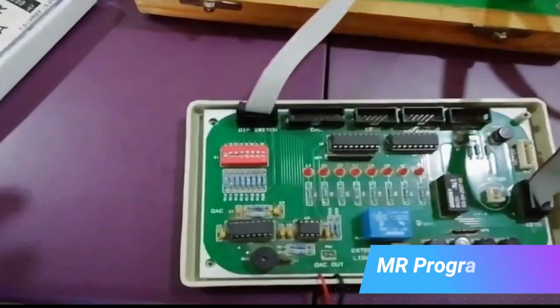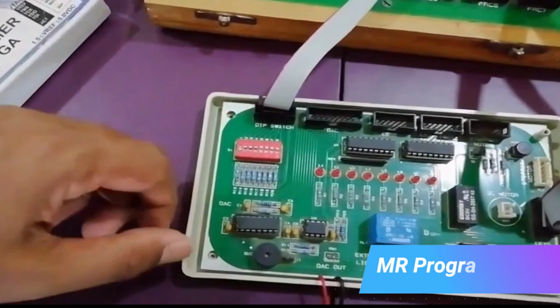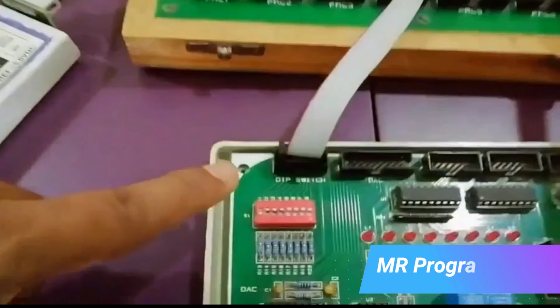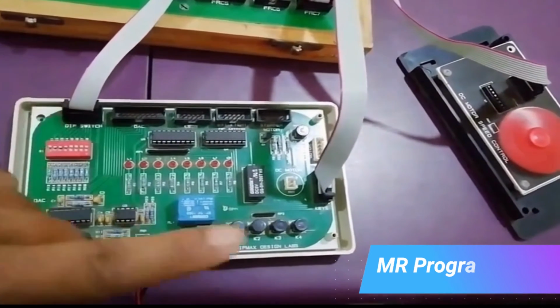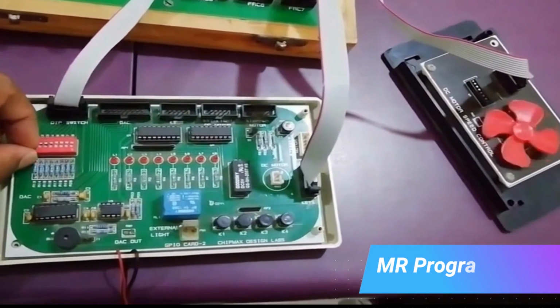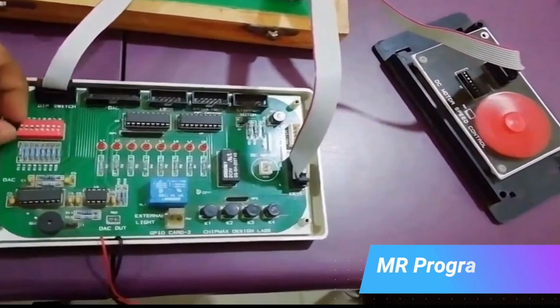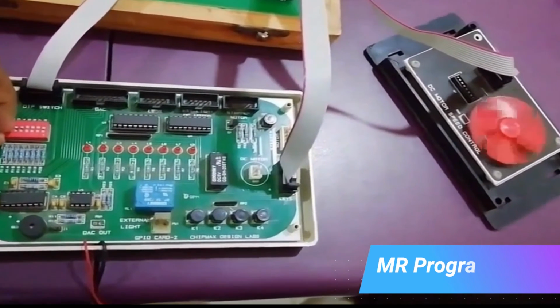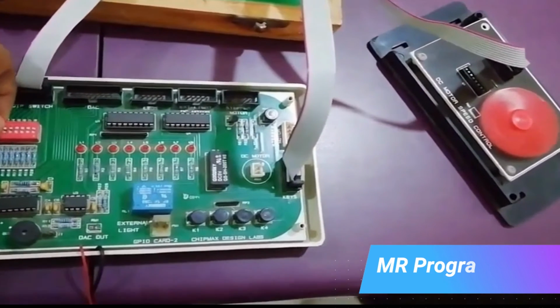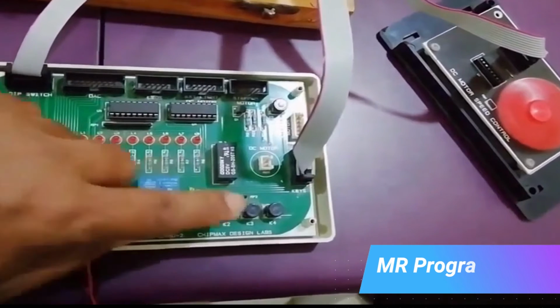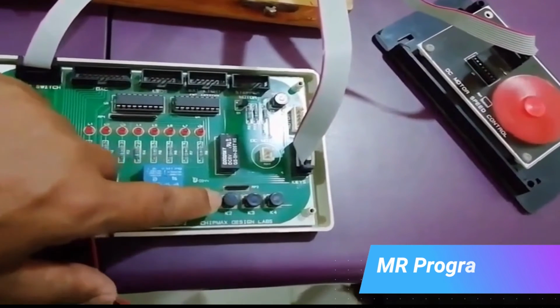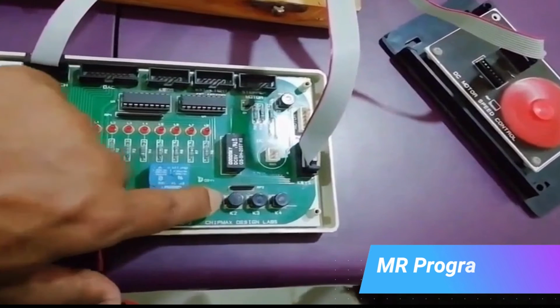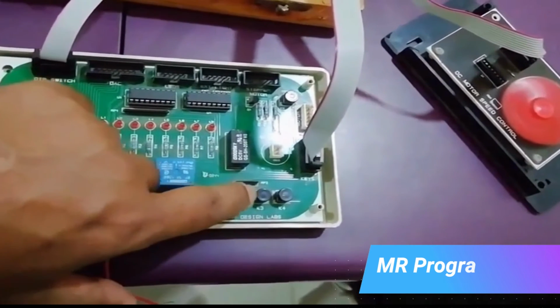You should be able to see program succeeded, after which this becomes fully functional. So that is the information that you should be able to see: program succeeded. When you turn on the switch, the DC motor should turn on, and you can turn it off as well with the same switch. The second switch is for the clockwise and anti-clockwise direction. And you see the push buttons at the bottom, the 4 black push buttons. These are for the speed control of your motor, as we had discussed in the program. So this is how your DC motor functions.